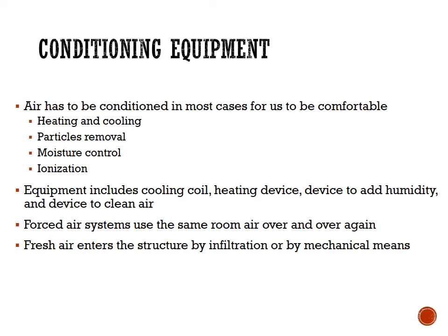Let's talk about the other topic, which is conditioning the air. We call it an air conditioner because it does not only add heat, it does other things. We can do heating and cooling, and particle removal like dust. We also do moisture control, where we can add humidity or dehumidify the air. Whenever you do cooling, usually there is a dehumidifying factor, and you always need a condensation pump because you will collect some water.